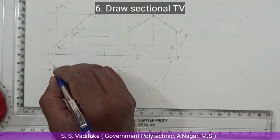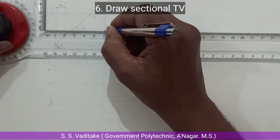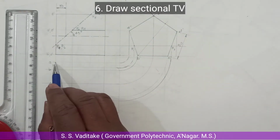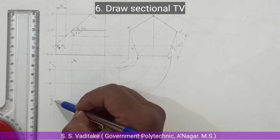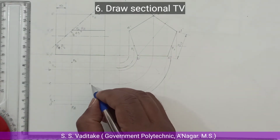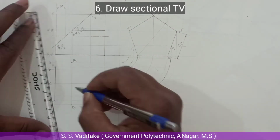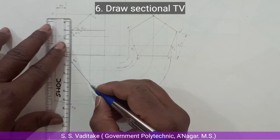So shift this in the top view and locate it as point 1. Now transfer the points A and D in the top view where they will cut the respective edges. Then point E will cut the edge E in the top view. So the 5 points we have located in the top view